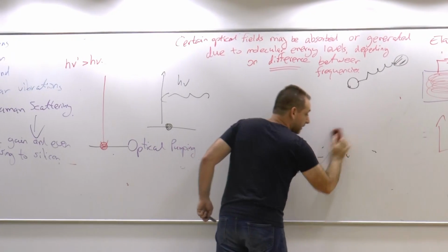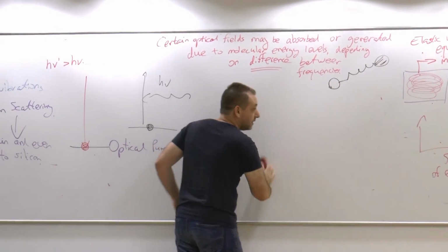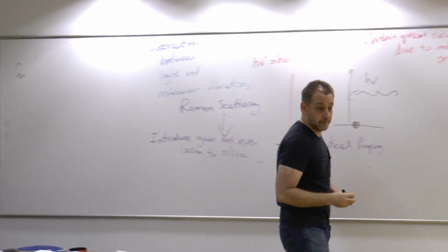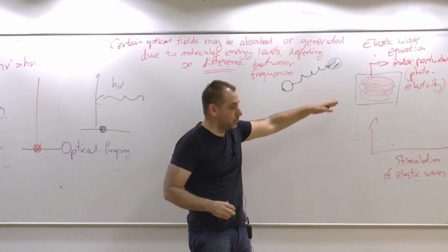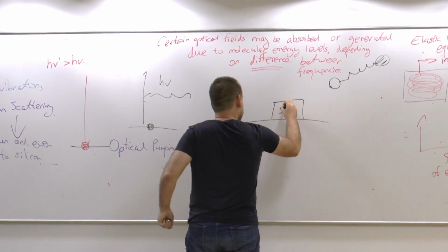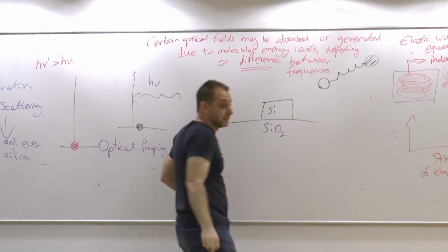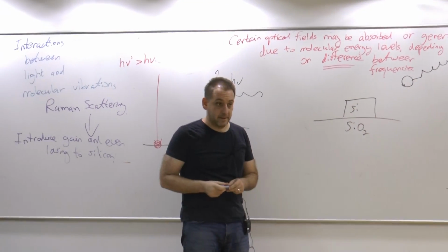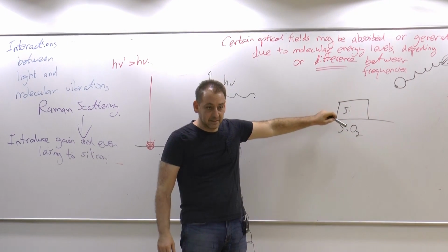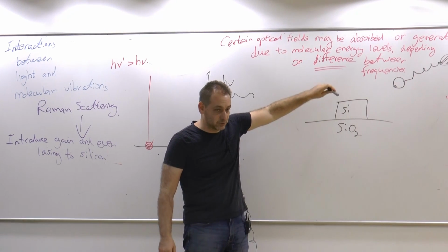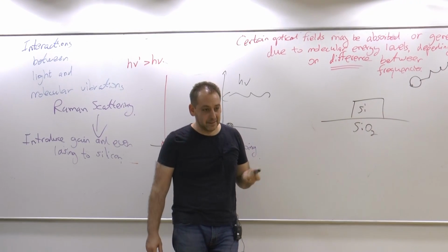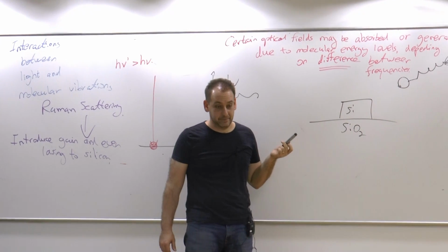Why was this mental picture broken? Because it turns out that in SOI, there are no modes like this. What we actually deal with is silicon and silica. And we have a very large difference in optical indices between silicon and silica. This is why we can confine light here and it does not run away. Mechanically, it turns out that silica and silicon are very similar.